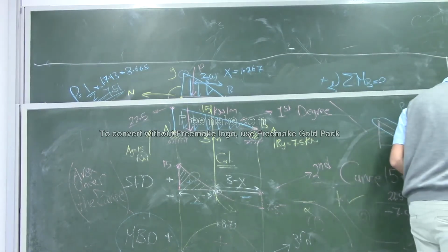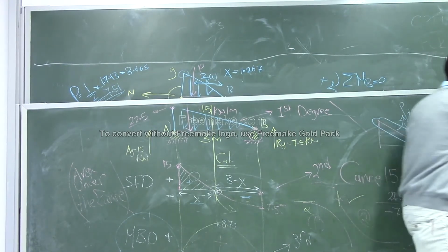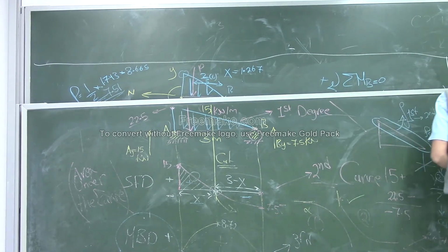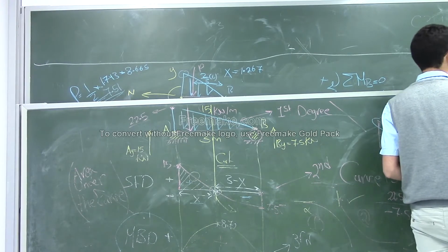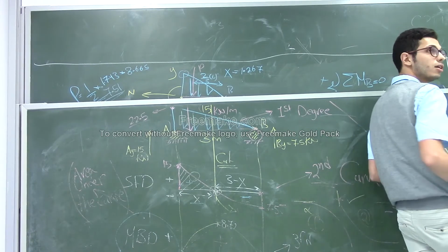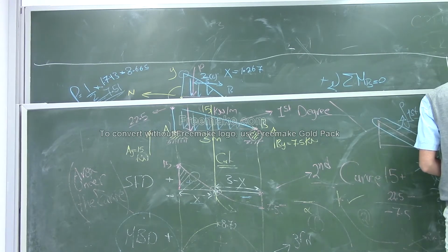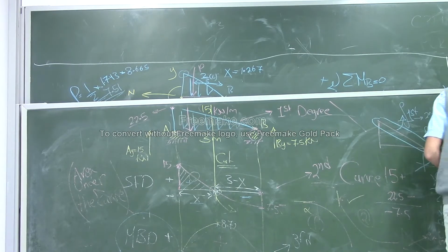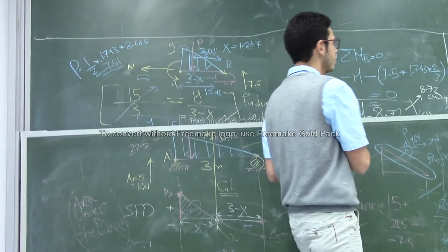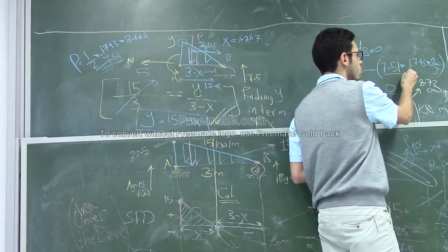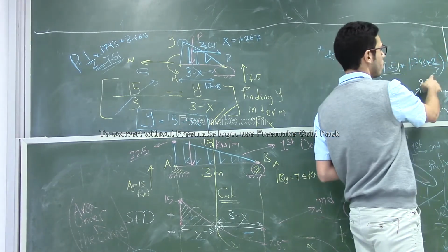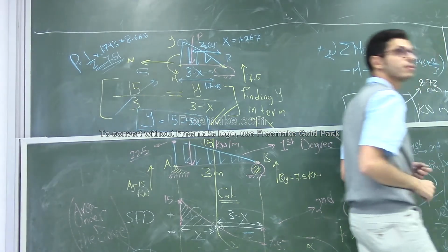So the load here is P. I want to find the point here. How much is this distance? As I said in the last lecture, from this distance it will be 1/3 multiplied by L, and from this distance it should be 2/3 multiplied by L. And this is it. You got your answer? Yeah. So now when you find the moment, 7.5 is the value of P, multiplied by this distance, which is 2/3 multiplied by this one. Good.